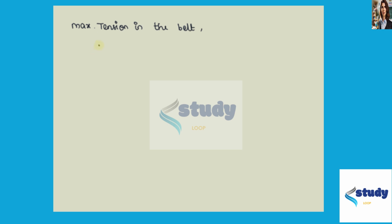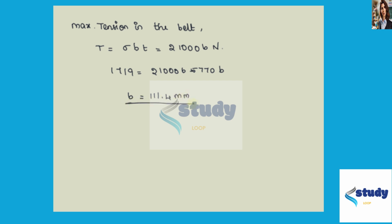Then next, the maximum tension in the belt is equal to stress into area, which is equal to 21,000 B Newton. So in total we get 1719 is equal to 21,000 B minus 5570 B. So we get B is equal to 114.4 millimeter. This is the width of the belt that is required.